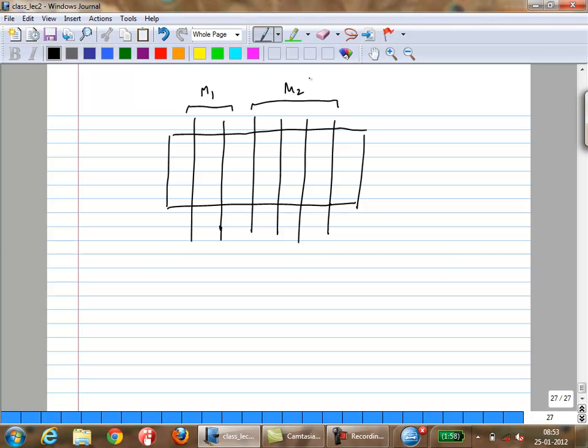Okay. You're taking care of these, yes. These are the gates. Remember, we looked at the gate, drain, source connections, the layout view of a MOSFET in the first or second class. Okay. So these are the gates. These are the drain source connections. Right. This is basically the top view of the transistor. Remember this? Okay. So this is the width of the transistor. This is the length of the transistor. So the width, this is the gate. So the thickness of this in the top view is the length of the transistor. We looked at this in the first class. Does anybody remember that? Okay, at least some of you do.